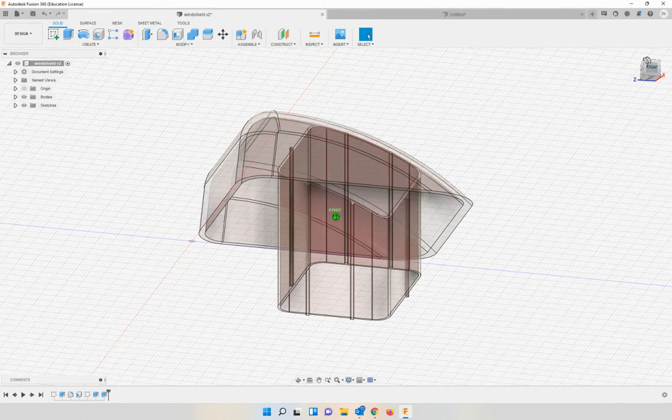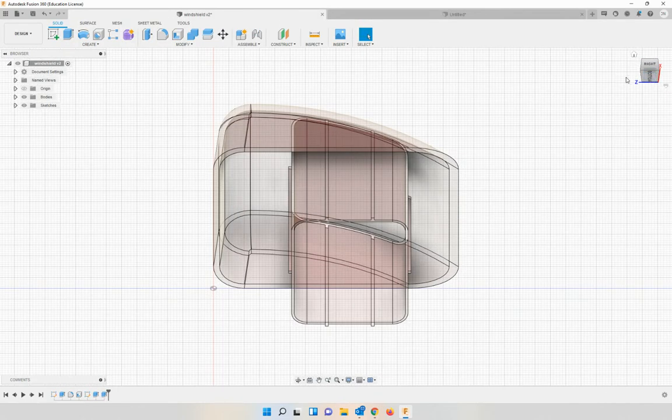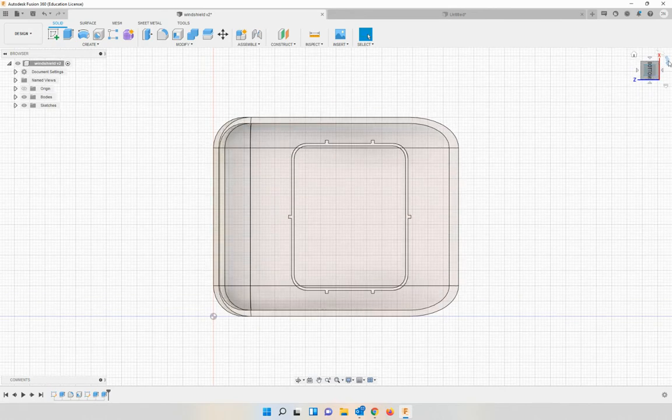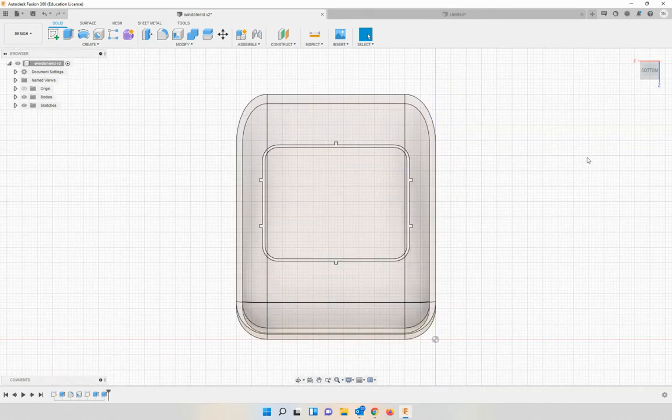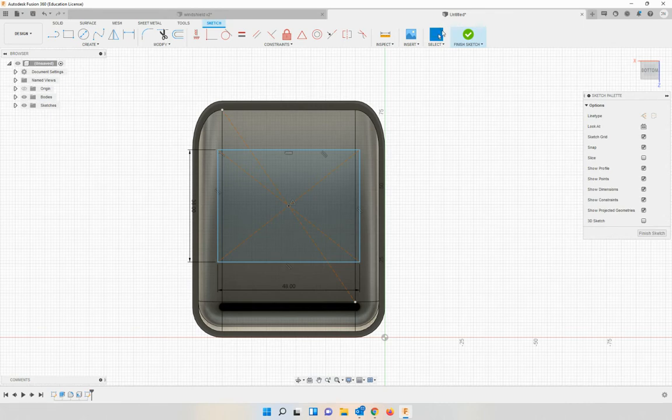Let's go to the bottom view on this one. Didn't get it. Let's rotate it around so we're in the same orientation. So these corners are rotated, and now we need to create these notches. But we need to do something else first. Notice how that's a solid shape. I only got a single line. So we need to fillet our corners, 5 millimeters, and then we're going to offset our shape by a millimeter, -1 millimeter.